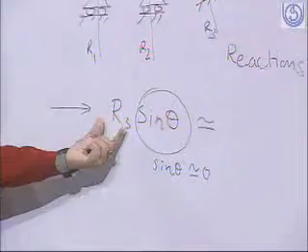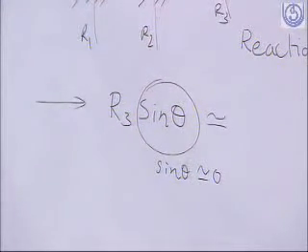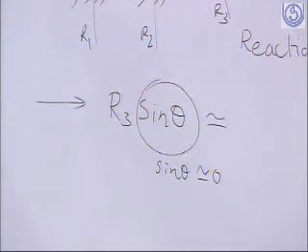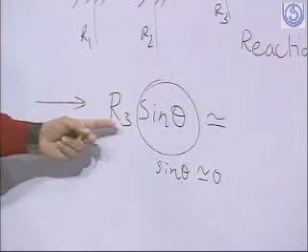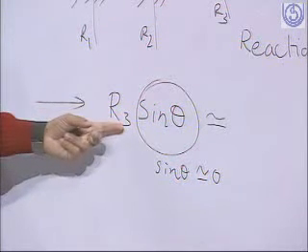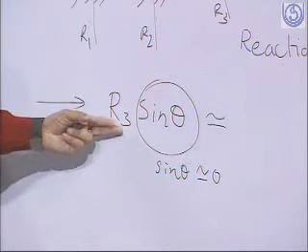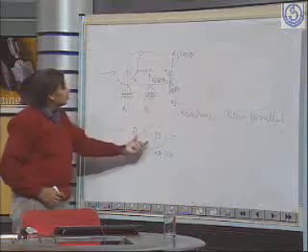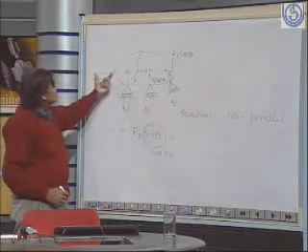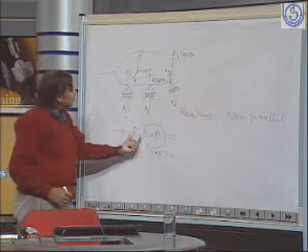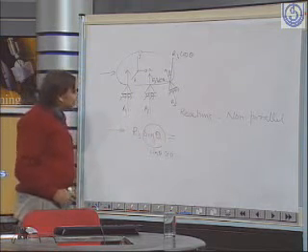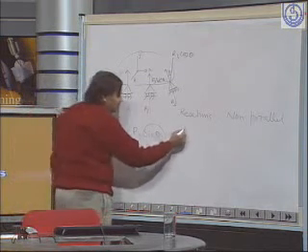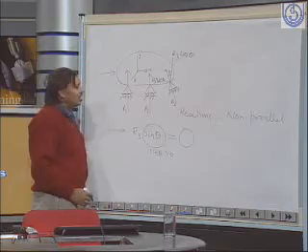So in that case, if you are putting even a small force in x direction, you require a very big reaction component R3 here to resist this small force, because R3 sin theta should have an appreciable value.